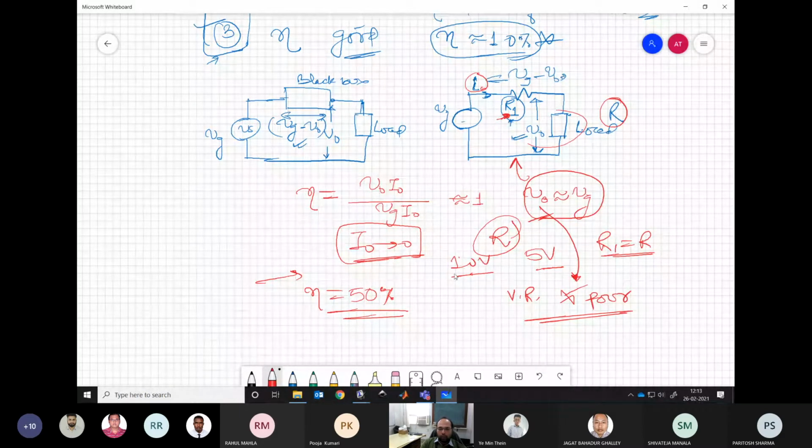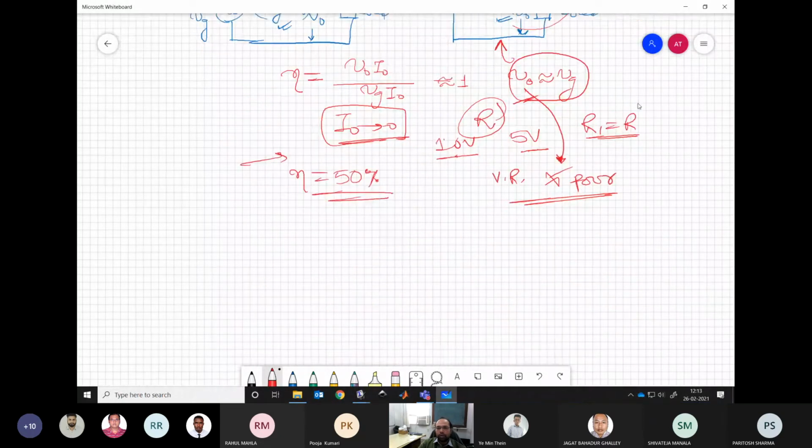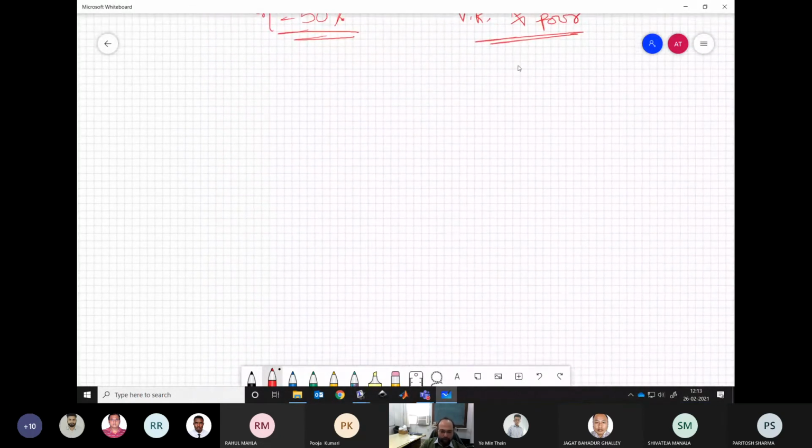So what it means is, if you want to apply this voltage irrespective of any value of load current, then we should have some way to vary R1, not the load. So a variable resistor could be there to take care of that. Let's say I call it RV, and the load resistor is RL.